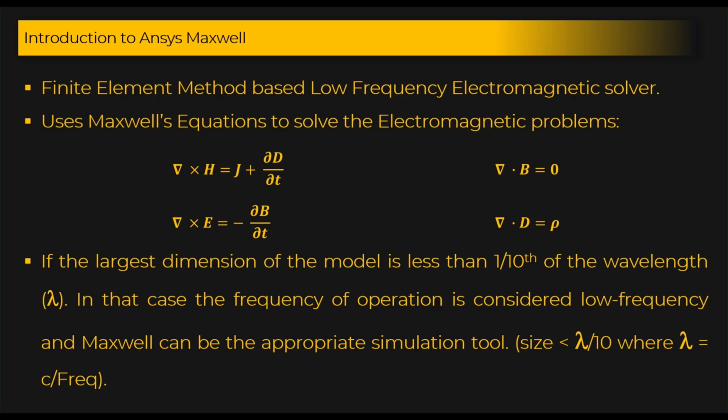So now the question comes: how do we know which frequency is to be considered as a low frequency? If the largest dimension of the model is less than 1/10 of the wavelength, then that frequency of operation is considered as a low frequency. And in those cases, Maxwell will be an appropriate simulation tool to go with.